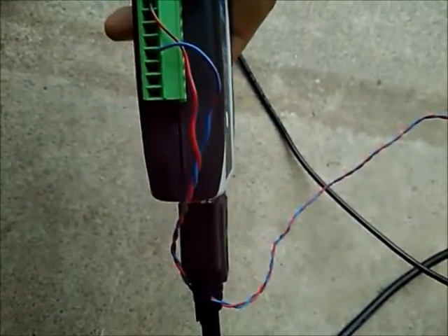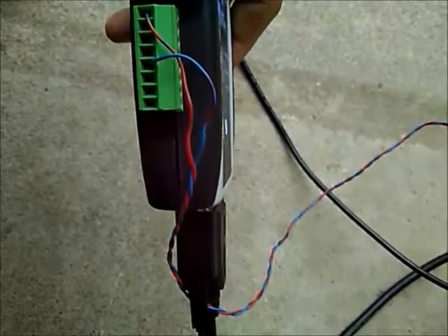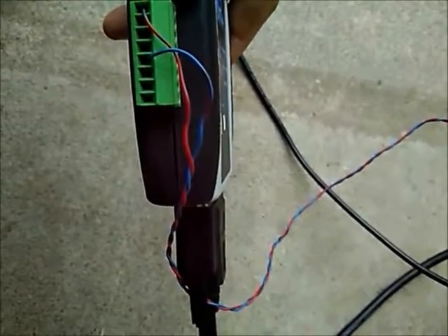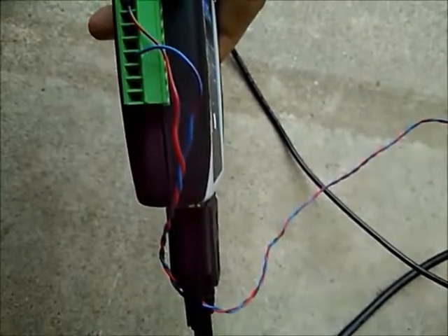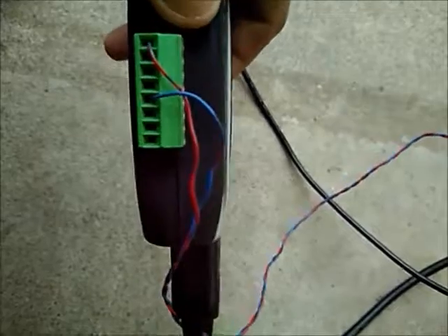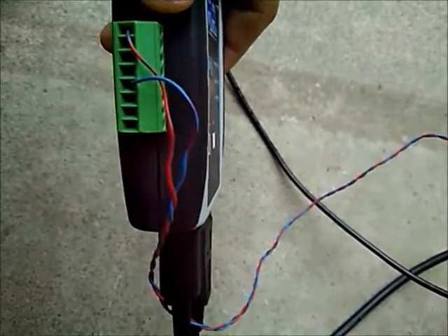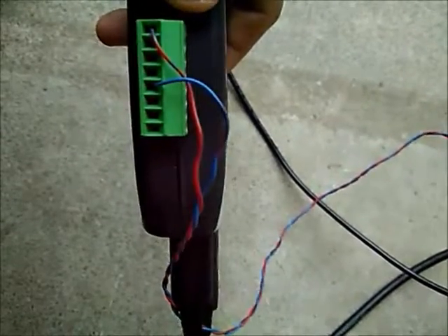So they have a lot of sources of noise. That twisted pair will help keep your signal a little bit cleaner. But if you've got shielded cable, coax, anything fancy that you can break out into wires at the terminal block here and still connect it properly, go nuts. The better the wire, the better the signal is basically what I'm saying.